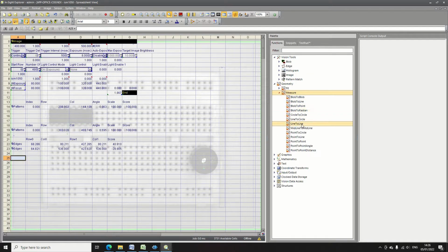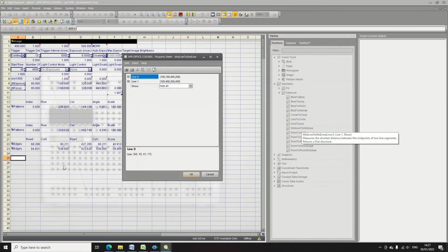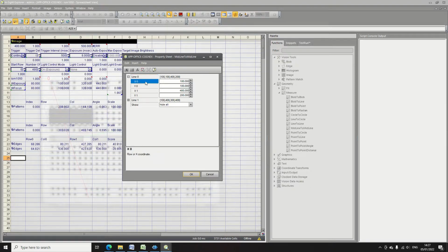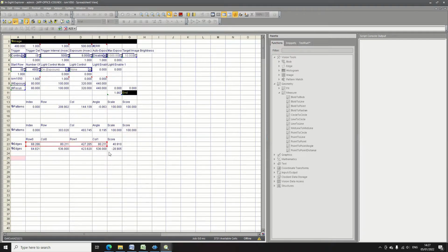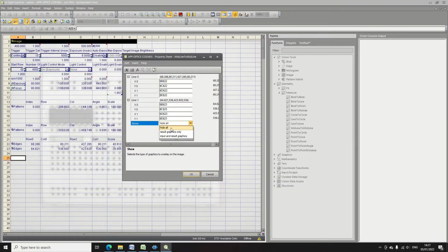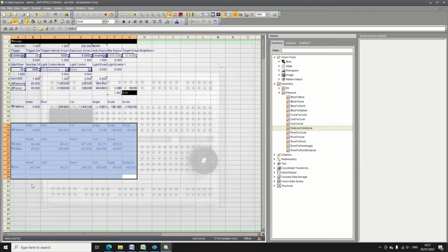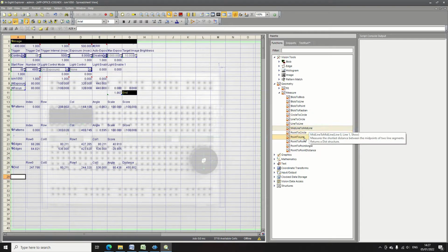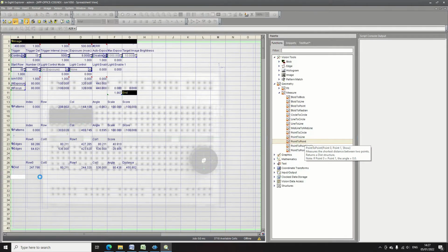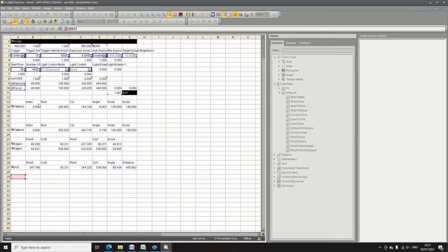Now that we have an idea of where everything should be on the board, we can do some measurements. So I'm going to measure the edges. This could be like a default. The reason why I did this is, after the measurement, if the measurement ever changed, which it shouldn't, it would mean that the camera has moved up or down or is out of place and would have to have maintenance done. But this isn't a key process parameter. The key quality attribute we're looking for in a moment is going to be a distance between the IC and the buzzer.